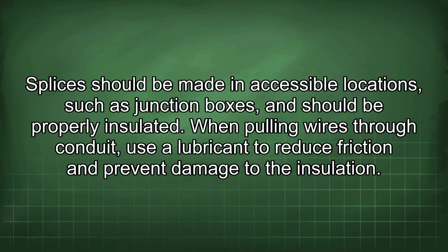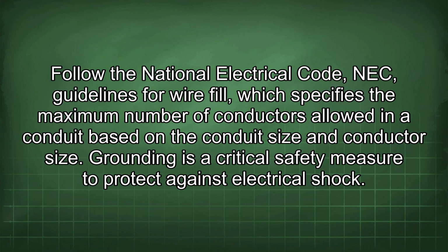When pulling wires through conduit, use a lubricant to reduce friction and prevent damage to the insulation. Follow the National Electrical Code (NEC) guidelines for wire fill, which specifies the maximum number of conductors allowed in a conduit based on the conduit size and conductor size.